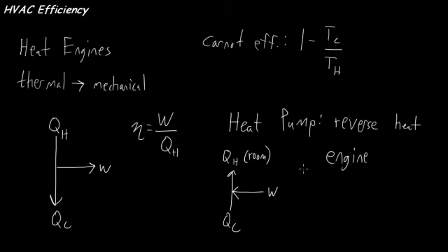Now I can run this heat pump in the reverse direction. It's a little bit tricky here because I said that heat engines and heat pumps are the reverse of each other, but there's actually sort of two reverses. If I reverse only the direction of heat flow, so let's say I've got the cold side here, which is still the room, and I am trying to make the room colder, I'm extracting heat from the cold side and dumping it outside. To do that, I still have to supply mechanical work.